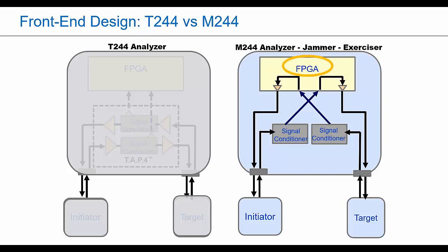The SerDes on the jammer is the link partner. It behaves just like a valid 24 gig SAS PHY. Only after it detects that both cables are connected is it going to actually start the link bring-up sequence. It goes through all the speed negotiation windows like a real device. It'll interpret and respond to any TTIU requests. It goes through receiver training directly with each side.